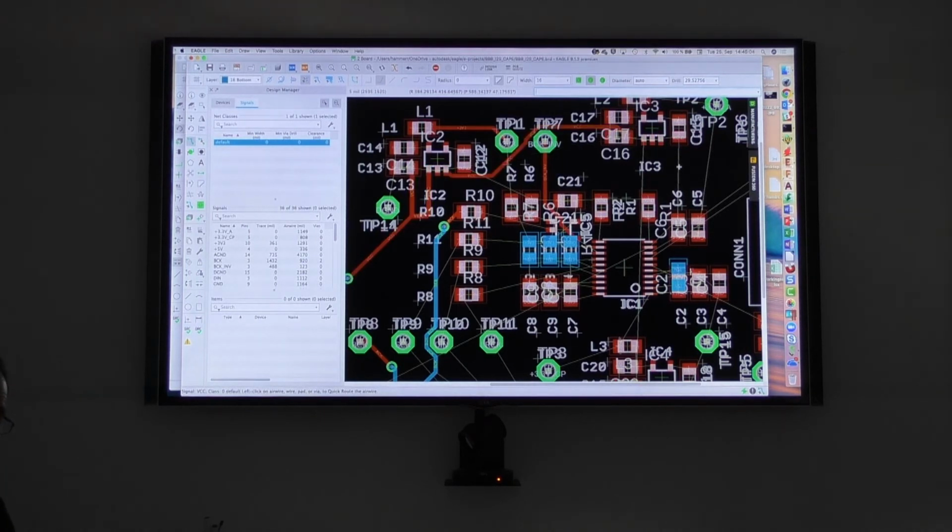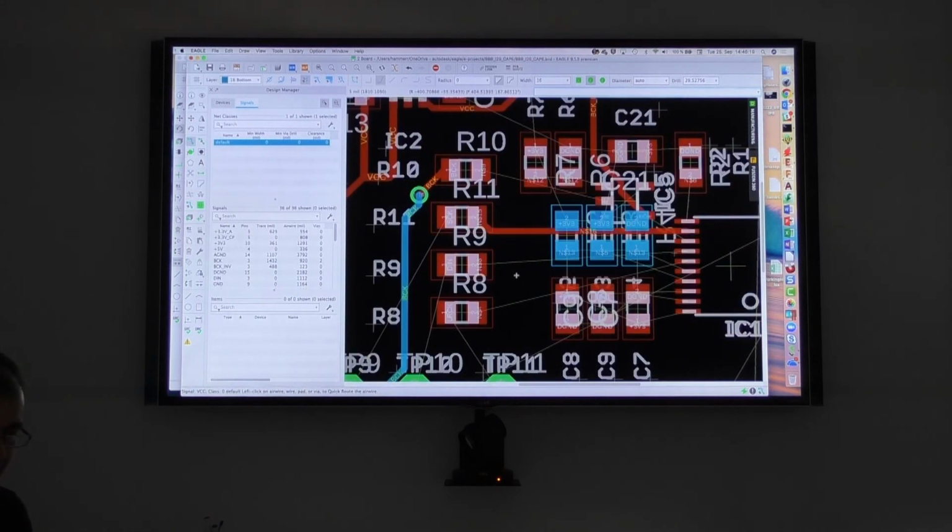This quick route does not take care of the current bit setting, so it decides on its own. There's a kind of artificial intelligence. You see, I get click, click, click. That's the student mode, as soon as the student realises that it exists. If it's good or not, that's something you have to decide, but basically it follows the design rules, and that's it. So it's a quick autorouter, a manual autorouter. Sorry.